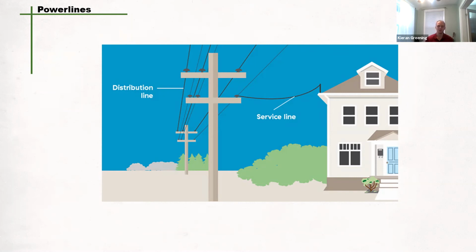And like I said, part of any good hazard assessment is to ensure all hazards that are serious are controlled. So this can include work with those power lines. Section 22 in the OH&S rules and regulations sets out a table with a whole bunch of different numbers relating to how close you can work to a power line if you're trained as an electrical worker. And if you're not, since the vast majority of us in the construction industry are not electrical workers, it's our best practice to ensure at minimum we stay away from that.